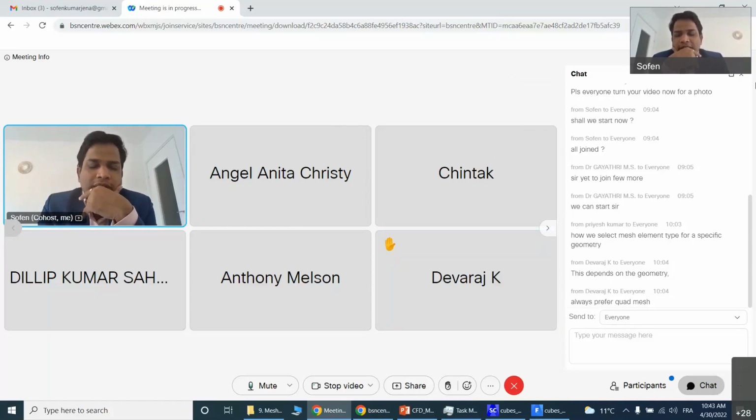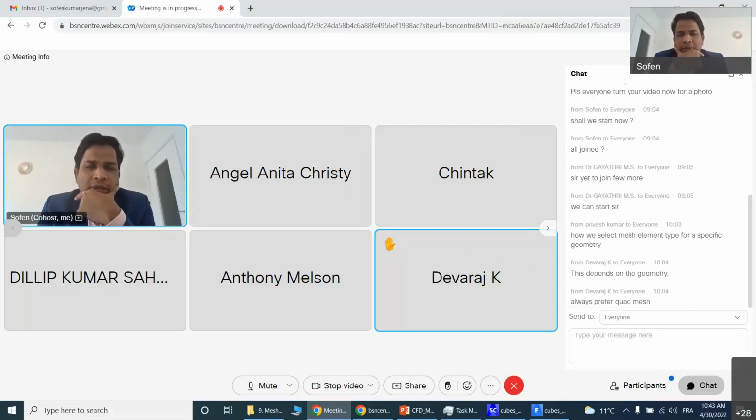The mesh is always attached. Once you do the meshing in the Fluent mesher, you will always get conformal meshing, and you will find the mesh is attached. In the Fluent mesher you can choose poly meshing, hex core poly meshing, or tet meshing. You cannot choose tet for one part and hex for another part. But in Workbench, that functionality is still there. You can use sweep mesh, poly mesh, those kinds of things. But again, doing that is not something where you have a connectivity issue.